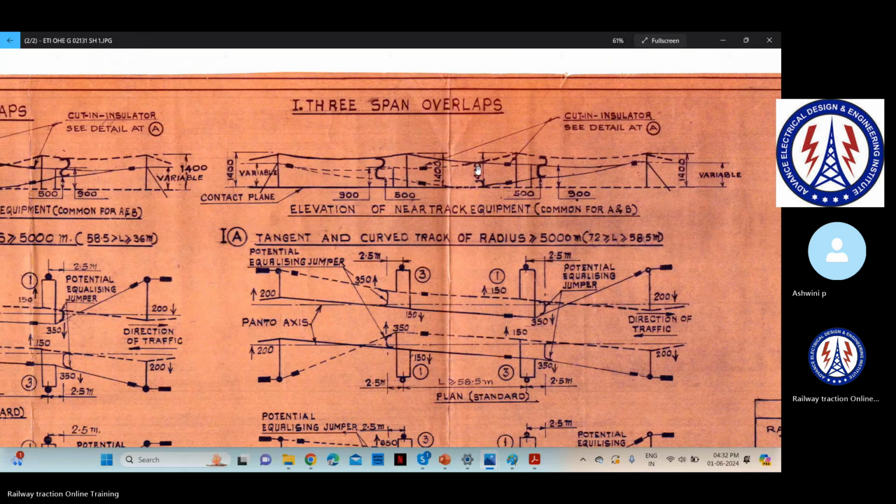Am I right? Okay. Yes. And if this wire is dead, I will make sure that there is an insulator over here also, because this wire will be crossing the wire. So I don't want two wires at different potentials. I want them at the same potential. That is the reason why this F jumper has been provided over here.